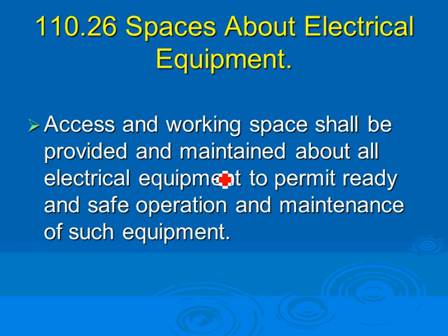Can you still load that 60 amp breaker to 80%? It's limited to 80%, yeah, continuous load limited to 80% of that rating. But in a house, there's no continuous load. Lights are the only continuous load. Receptacles are non-continuous loads in a commercial building or anywhere else. Typically these circuits are lighting and receptacle loads. So yeah, you have to limit it.